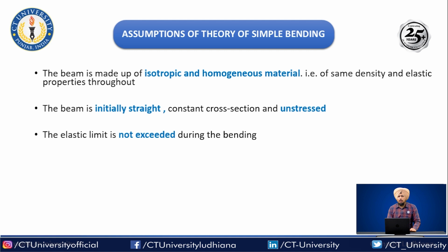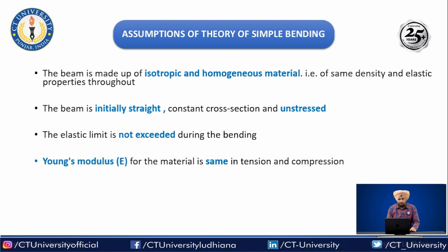The elastic limit is not exceeded during the loading time, so we are staying within the elastic limits. The Young's modulus of the material is the same in tension and compression. In the upcoming few minutes you will see that there are two types of stresses in the beam. When it is subjected to loading, there might be tensile stress. In some layers we will have tensile stress, and we also have compressive stress. So we are assuming that the Young's modulus of the material is the same in tension and compression.